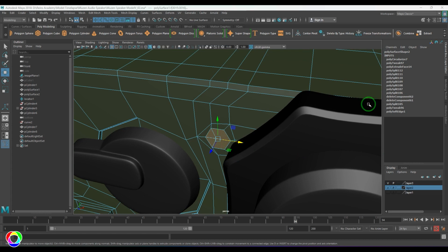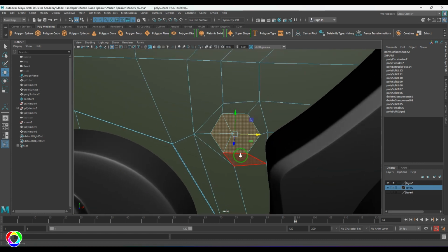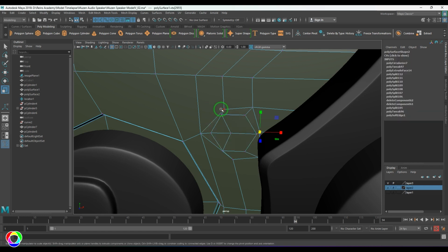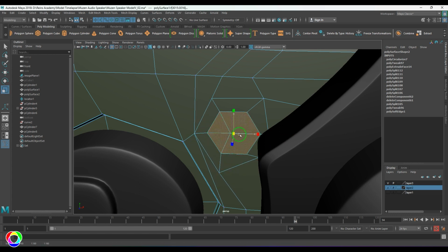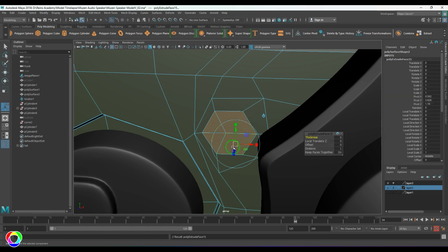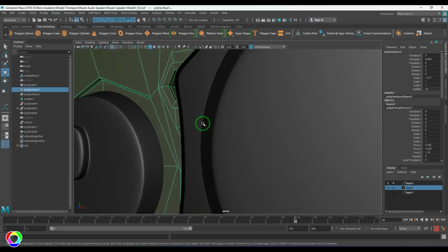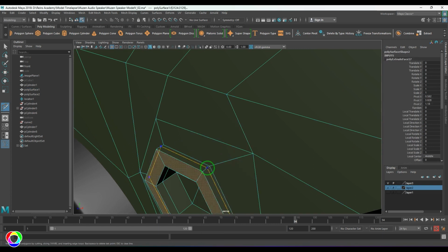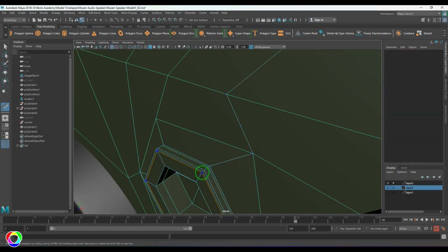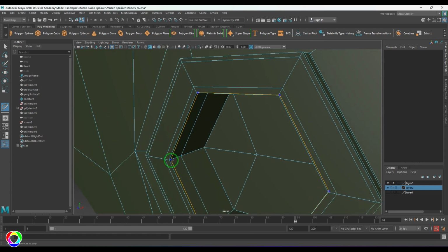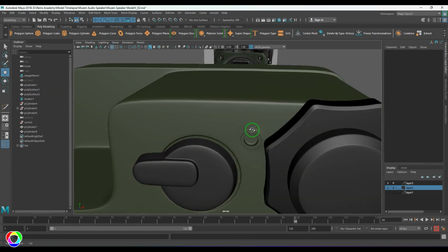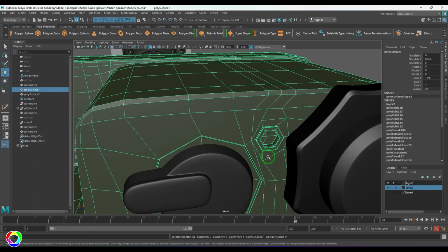This is a face with some rib, so I'm going to scale it slightly, adjust those points, scale those faces, press Ctrl E to extrude, and then extrude it. I'm going to select these faces, extrude it like that, and add some lines there, which gives this nice detail.